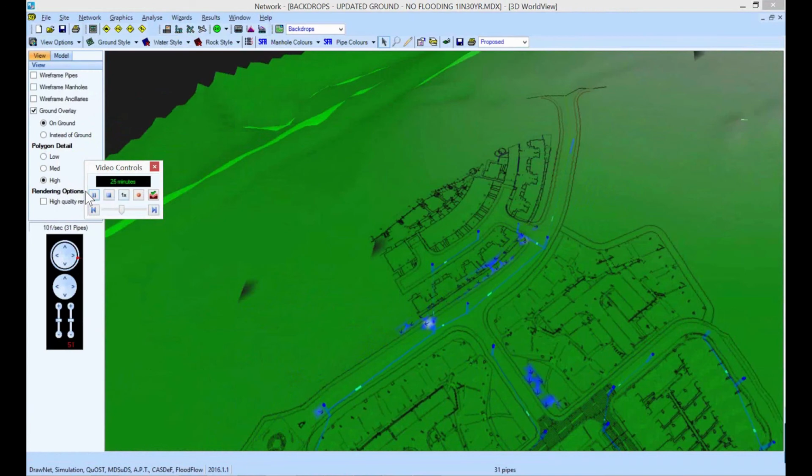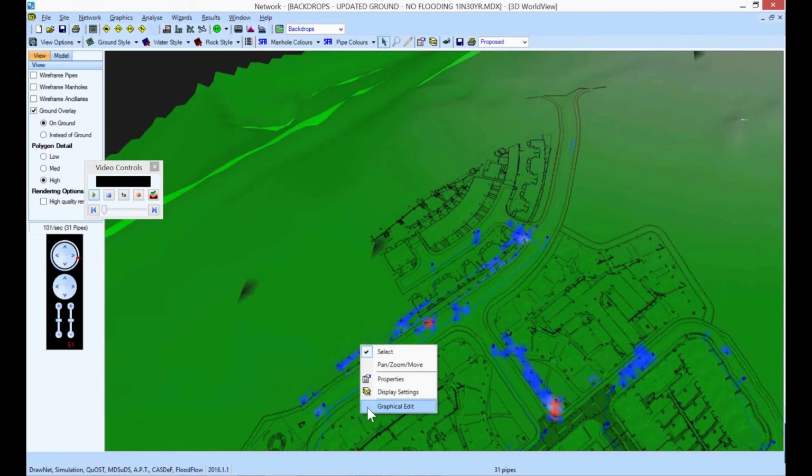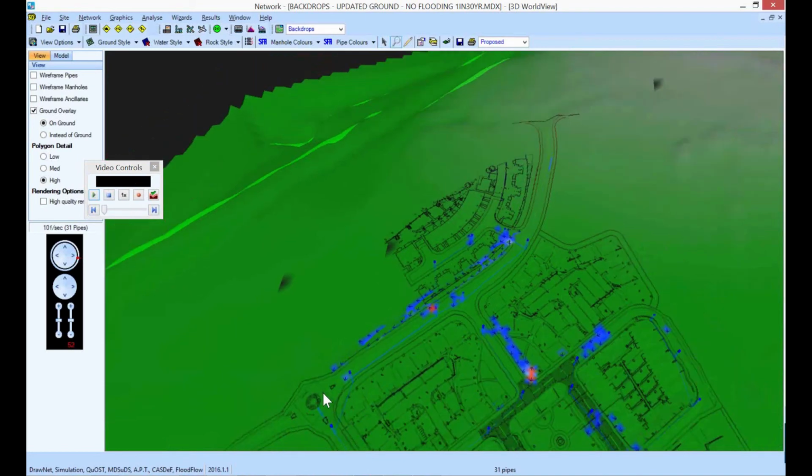So we've got the surface water flooding now, and that surface water flooding is actually starting to make its way across and down this section over here, all the way down to a point lower down the network. So it's being channeled by Dan's road design here until we get to the flatter area of the roundabout with its area in here. And actually, we specifically put some manholes in here. And if I showed a slightly larger depth of water going in here, what you'd see is that it's actually being collected and reintroduced into the 1D network from these manholes down here.